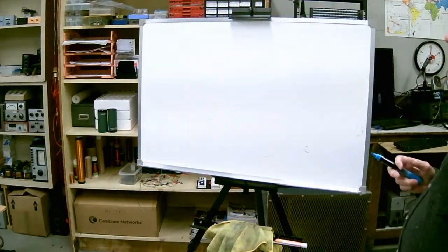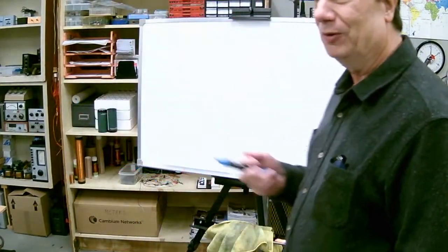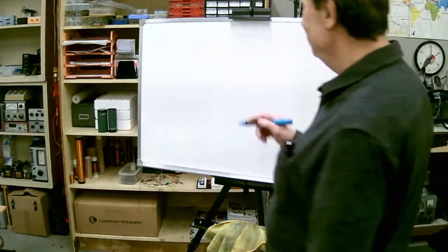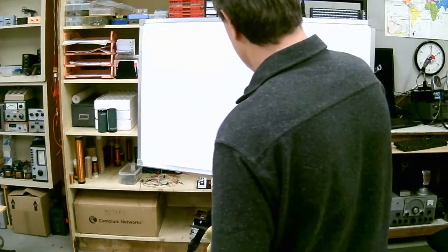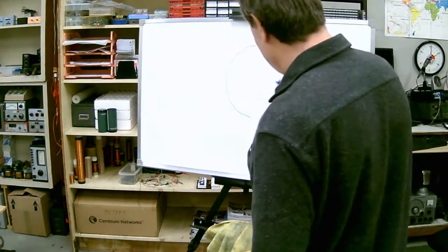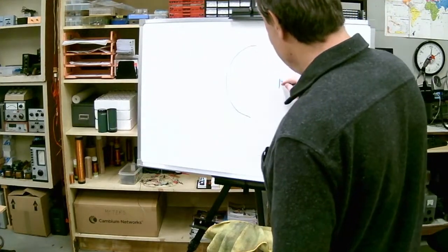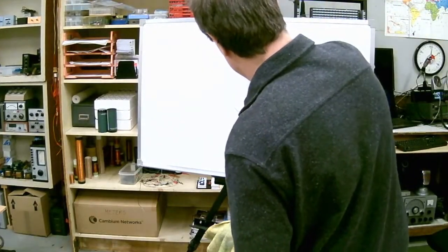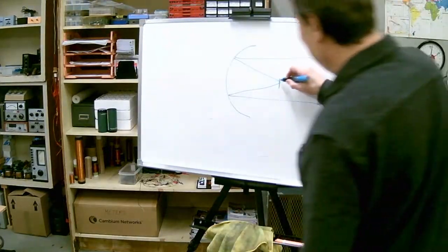So, we talked about the fundamental antenna. Everything uses that as the basis for any kind of high gain antenna you want. You work with satellites a lot and use parabolic dishes, right? Generally at the focal point here, we have a dipole of some sort. Sometimes that'll be actually aiming toward the dish. Lots of variation. But if we just have a dipole up here, that has a radiation pattern, the donut shaped thing, and anything that's radiated this way is going to be reflected off. And you get a semi-collimated beam out there.